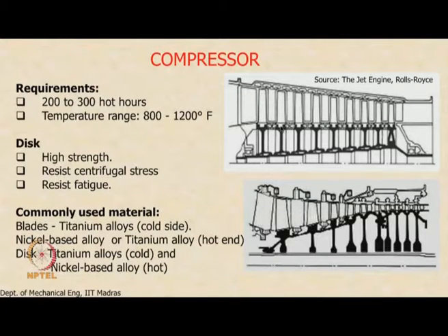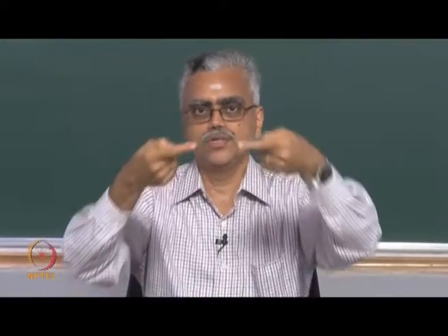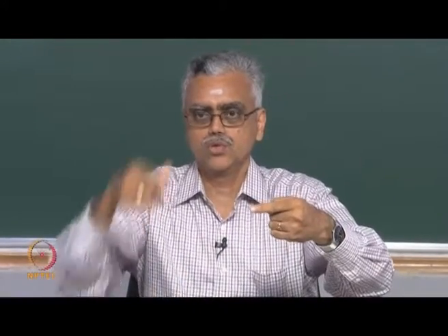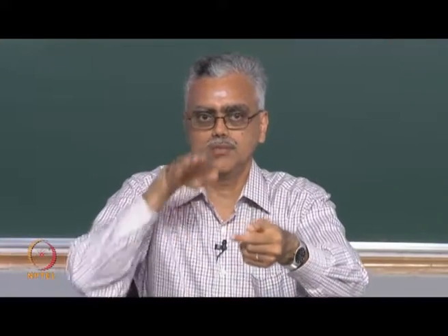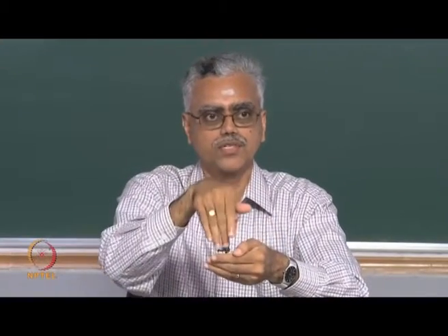So what happens is, if you assume the disc is like a band which is circumferentially arranged like this. Let us say that the shaft rotates like this. So the disc is a band like this. You make a circumferential groove, and the blades are then slid into the circumferential groove, and that is what is done here. You can see the blade in the circumferential groove in this cut section view.